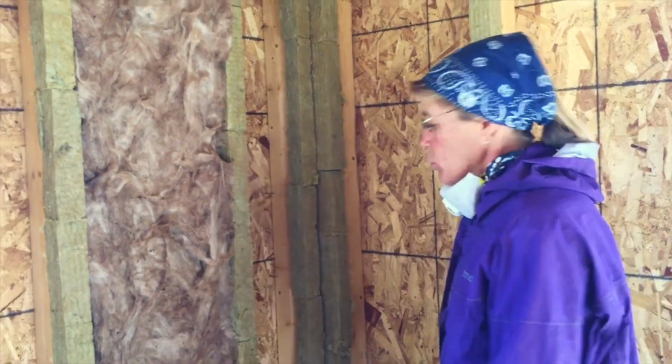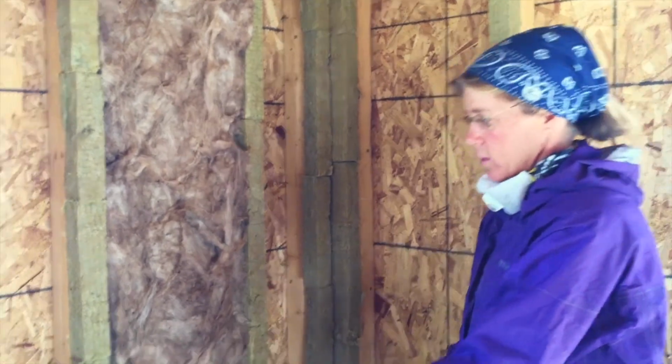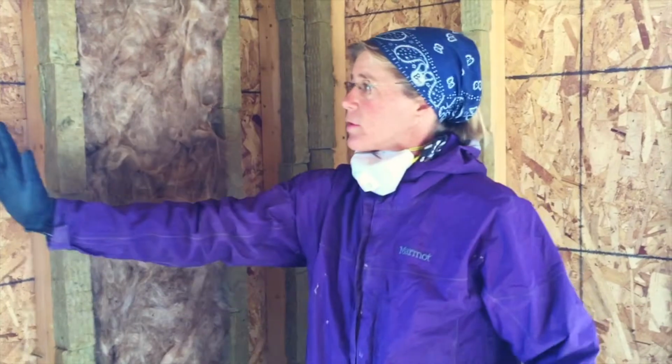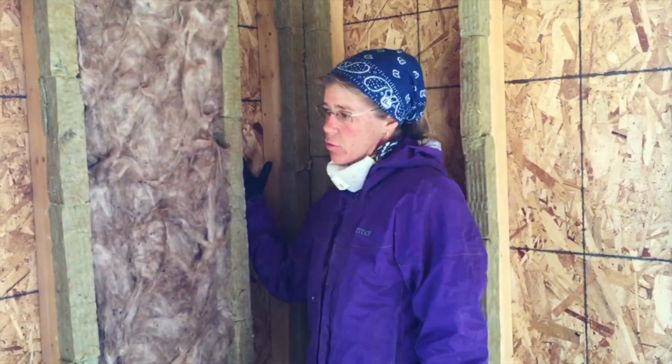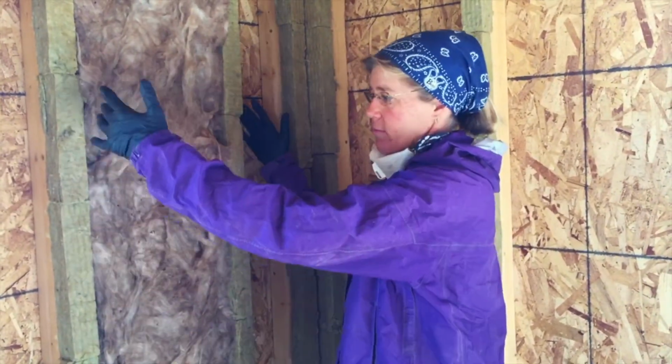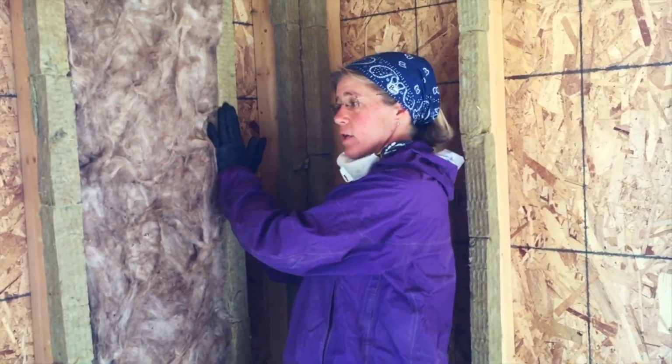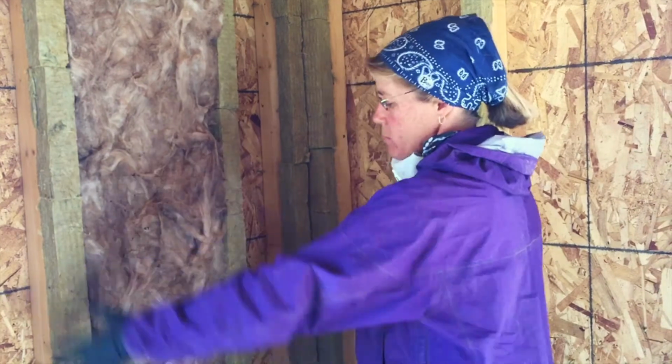Another type of insulation I don't have pictures of is blow-in insulation. This is really common in attics. You have to rent a blower and then you get either fiberglass or some sort of paper or recycled material that has been treated with a flame retardant. Do your research on what you're comfortable with. But blow-in insulation is a great option when you have big spaces.